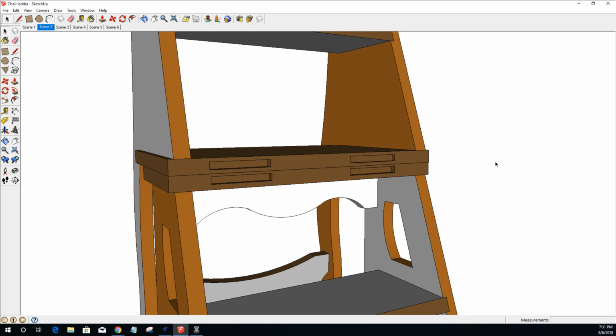And so you would have 2 mortises where that concealed hinge mounts into. They're not very deep. I think it's only like a 1/4 inch deep or something like that. And they wouldn't be square. They would have rounded corners, just like you saw in that picture of the hinge, and you would just mark them out. Now, those won't be done on the CNC. You would have to chisel or use a router table or something, because unfortunately we can't stand the boards up on edge to mill those mortises in.